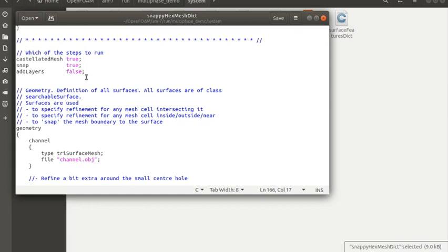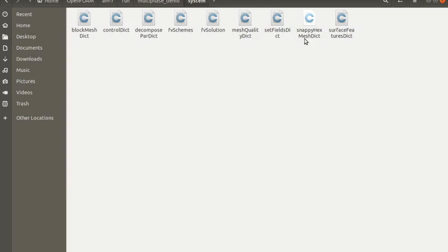So there will be, from the wall to some distance, a boundary layer where we have to get the correct calculation. So add layers will help in creating the boundary layers. Here I am not showing that process because I was not able to create those add layers in these complex structures. Maybe at a later stage I'll demonstrate how to create add layers in these complex channels. So that is about the snappyHexMesh dictionary. It's an important part of this simulation.